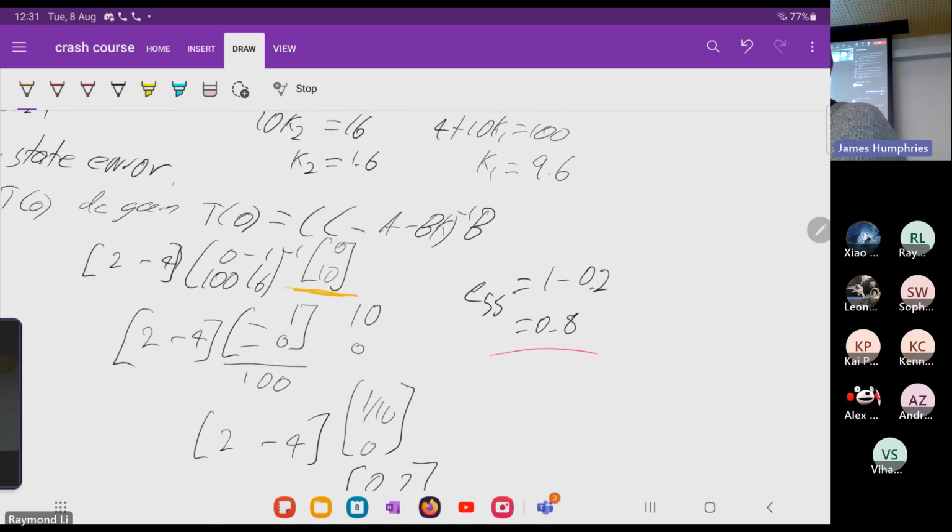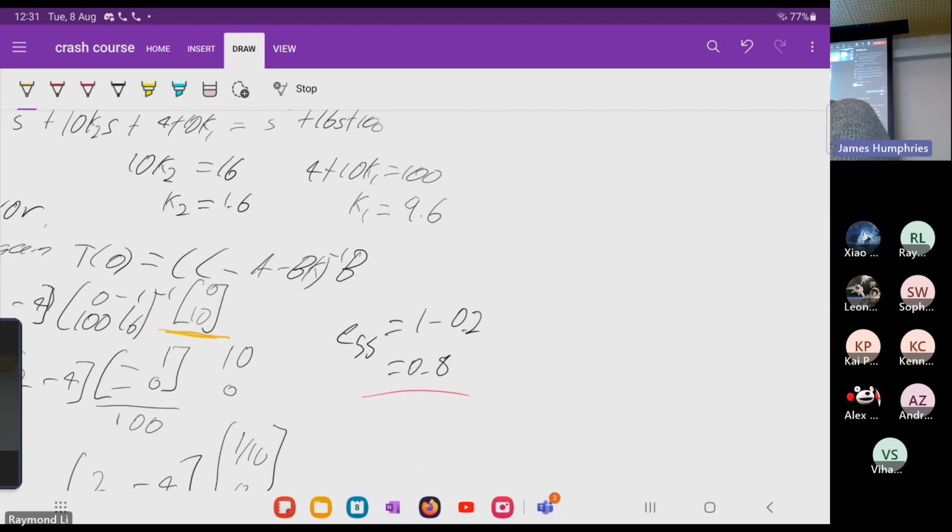So because there was a 0 here, I'll put it on the side here. We're going to have A, B, C, or D that we could have. And if I have 0 and X, then I'm going to end up with A times 0 plus B times X, and then C times 0 plus D times X. So you see how the values of A and C don't appear in the answer. And so as a result, that's why I consider them as don't cares, because they're just going to disappear.